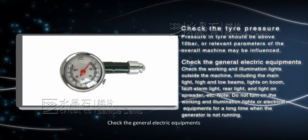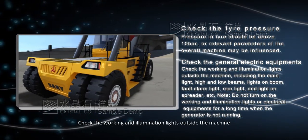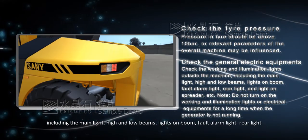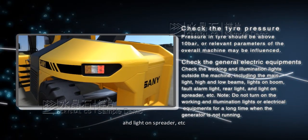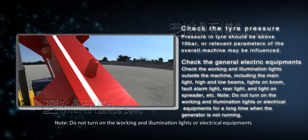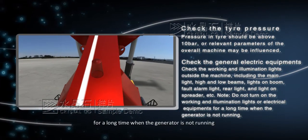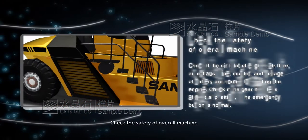Check the general electric equipments. Check the working and illumination lights outside the machine, including the main light, high and low beams, lights on boom, fault alarm light, rear light, the light on spreader, etc. Note: do not turn on the working and illumination lights or electrical equipment for a long time when the generator is not running. Check the safety of overall machine.